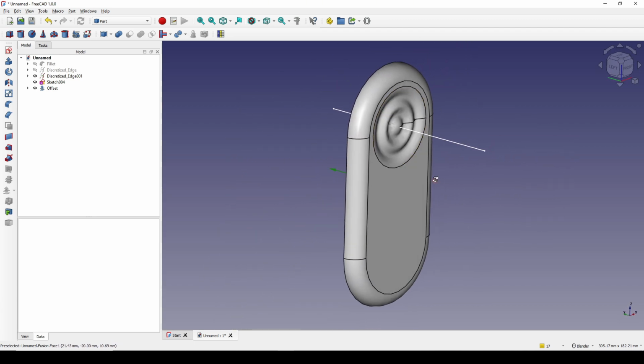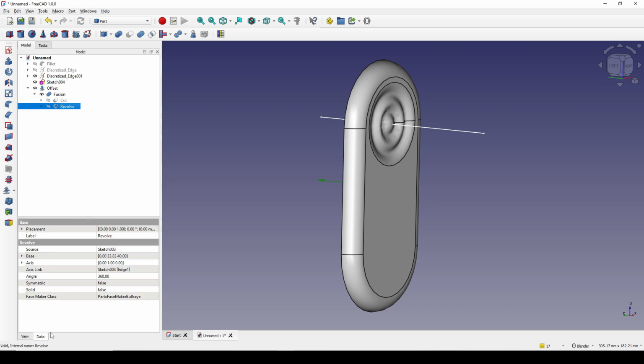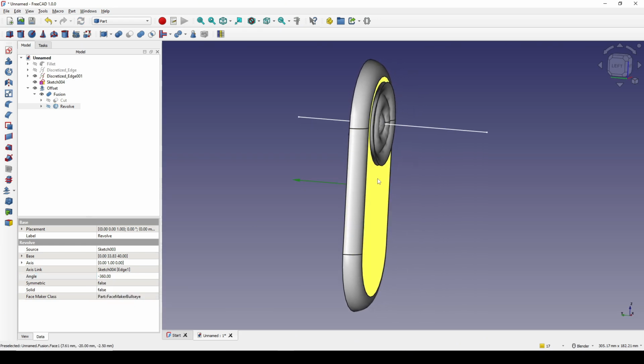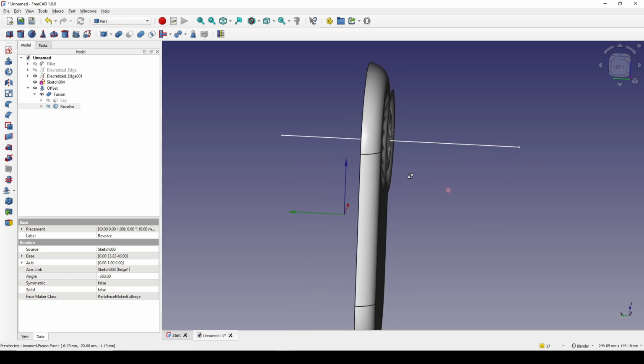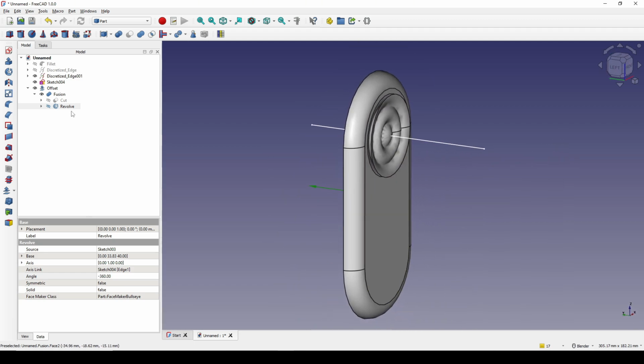Alright. So what happens if I go down here, drop this one down and drop this one down and click on the Revolve. And I go down to the data, and in here I have an option angle. What happens if I put a negative number for the 360 to revolve in the reverse direction? I click off, and you can see the 3D offset going exactly like the sweep I did before. So I turn this one back to the 360.